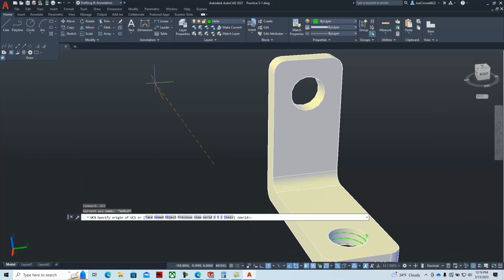I'm just going to type them in rather than change workspaces, and then I'm going to choose 3, and I'll start with a point here. It's the origin, positive x-axis, positive y-axis. Helix command, hover, acquire, there we go. And then we'll use those same settings where we'll make that 7.5, 7.5, and 7.5.